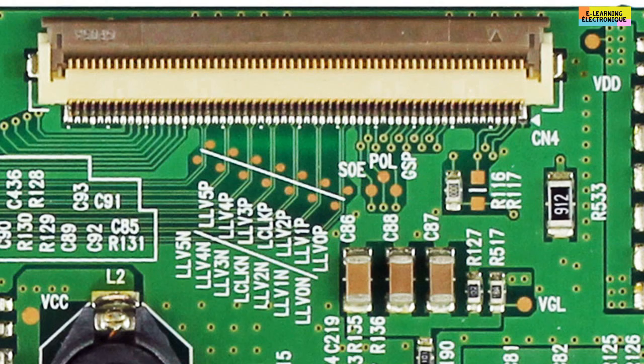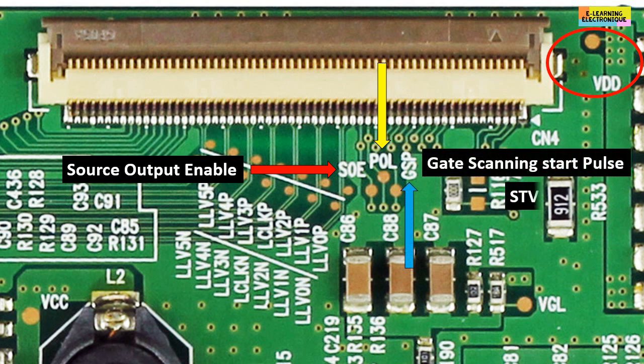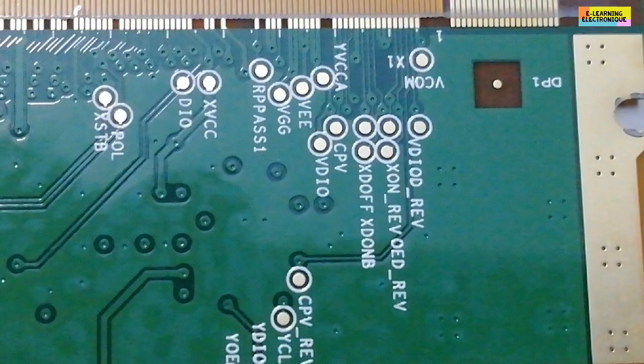On this TCON board, next to the polarity control signal labeled POL, there is the inscription SOE, which is the abbreviation for Source Output Enable. There is the inscription VDD for the digital voltage. For information, the inscription GSP is the abbreviation of Gate Scanning Start Pulse, which is nothing else than STV or VST. On this other board, next to POL the polarity signal, we find the STB inscription. DO is the abbreviation of Data Input Output. VEE is VGL and VGG is VGH.